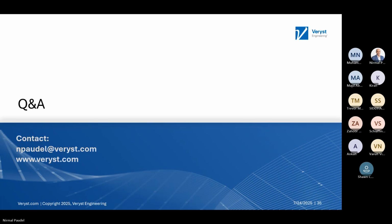There is also a question: I'd like to know how to generate the current or voltage waveform for a switched reluctance motor in COMSOL. The waveform of current required for a switched reluctance motor is completely different from that of a synchronous motor. I would say that generating the voltage and current waveform should be the same as long as you assign them as a coil feature, whether it's a stranded or multi-turn coil.